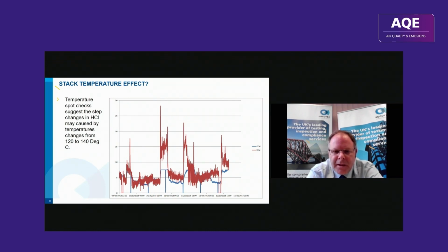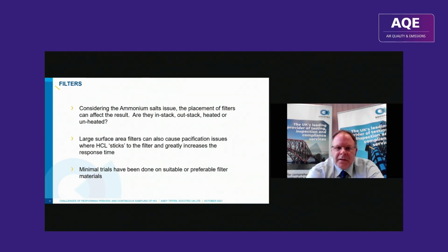period of time. But it's the step changes that were of interest because those step changes occurred as the stack was changed in temperature. Now, again, it's hard to say whether that was process related, but there is some suggestion there that changes in stack temperature is either breaking down and decomposing the ammonium salts into HCl and ammonia, or possibly that those are being formed into salts at lower temperatures and not being formed into salts at higher temperatures. So really the effect is to look at the sample system at the stack temperature and see what can be